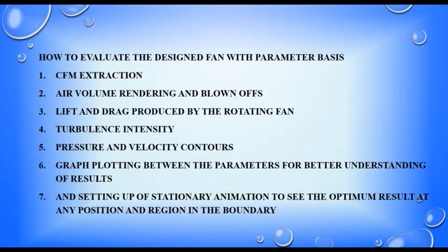Previously I made one video on CFD fan analysis, but that one is different, because at that time the fan was stationary, not rotating, and we applied a velocity of air, bombarding the air on the fan and calculating various factors. But here I am rotating a fan at certain RPM, and we will be checking in the result parameter how much air is delivered by the fan at what velocity within a defined region.